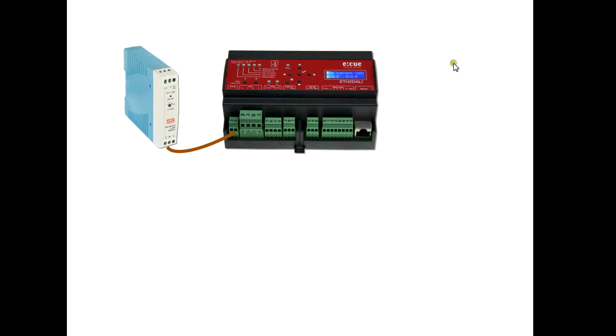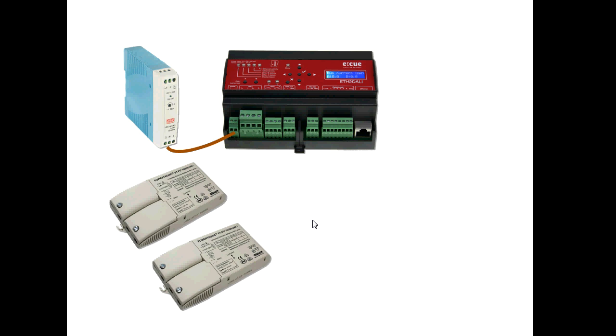The Ethernet to DALI can either be an interface for the lighting application suite, or it can run as a standalone engine without a LUS server. In this case, it is an interface and it has two DALI lines, it has one DMX universe, and it has digital dry inputs. Connected to the Ethernet to DALI are ballasts with a DALI interface. And these ballasts control various types of fixtures and lamps. There are ballasts available for every kind of fixture today.